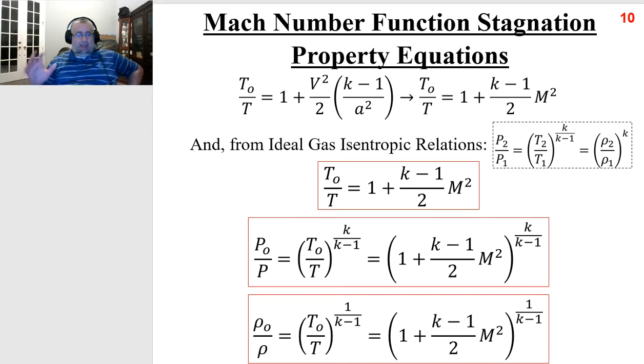So by combining, again, mass conservation, momentum conservation, the energy equation, thermodynamic equation of state, the ideal gas law, and the process path, which is this assumption of an isentropic adiabatic process, I now have an enormous amount of really useful information that I've gleaned from those 5 equations that basically tell me almost everything that I need to know about this fluid, this flow field that's operating at Mach number of above 0.3, where compressibility effects matter.